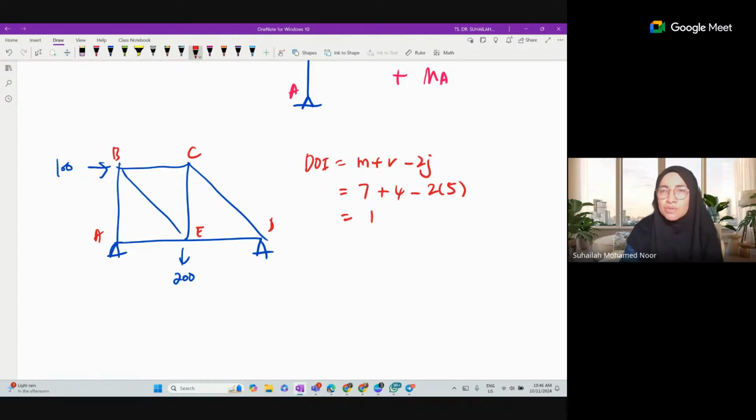To get a stable truss, it must have one pin, one roller. One pin, one roller means that we can have one redundant reaction. In this case, we have 4 unknown reactions and only 3 can be determined using equilibrium equations. So this means that the redundant comes from the support. There will be another case where a member force is the redundant. It is for internal indeterminacy.